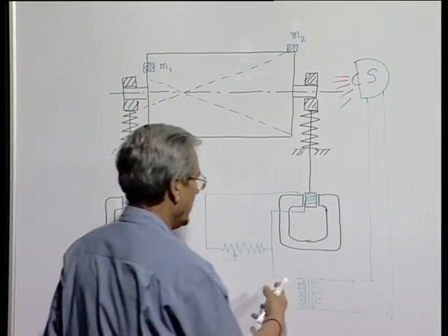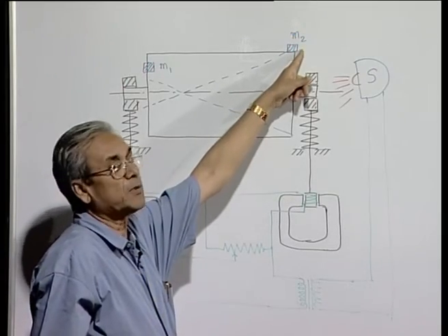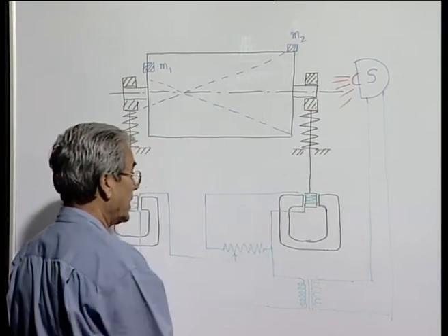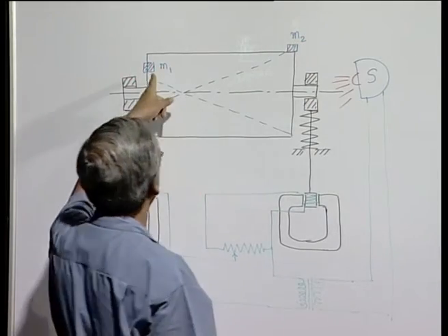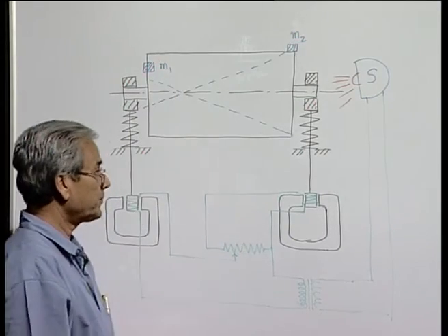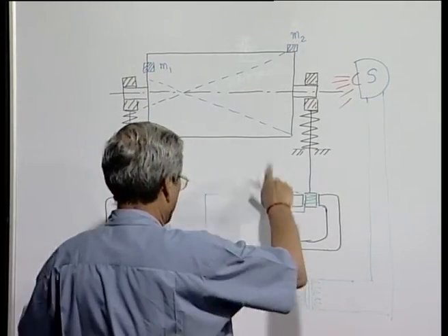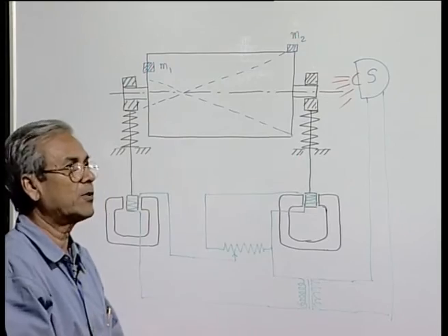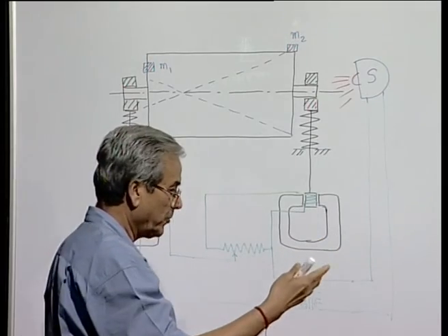So, effectively this circuit will now be insensitive to any unbalance produced at this end. Whatever effect or voltage comes here, depending on the location of this potentiometer arrangement, is due to this M1, which is really present, though temporarily we imagine it to be absent. Now whenever this moves up and down and this voltage changes its direction, this stroboscope will flash for 1 microsecond as soon as the sign of the voltage changes.